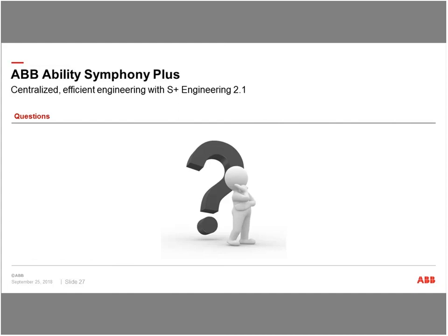For Symphony Plus Operation 3.1, this new operation engineering can help a lot. In the past, if you configured a tag in the Composer database, it was not complete. Some fields are not available in the Composer database, so you needed to work outside the Composer environment to do tag management.